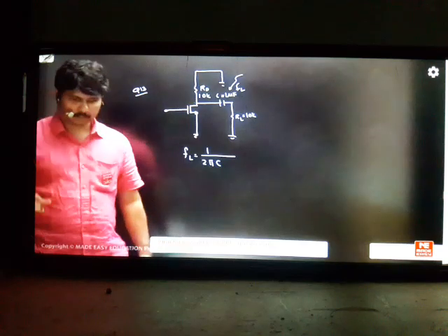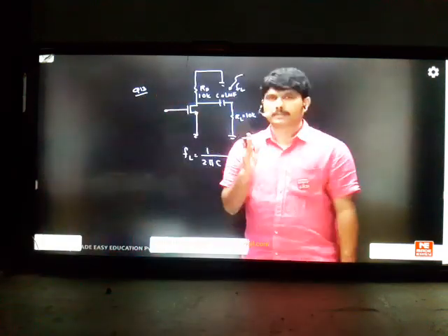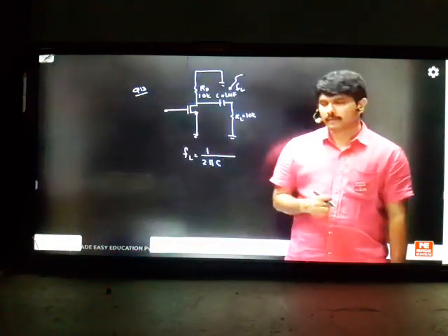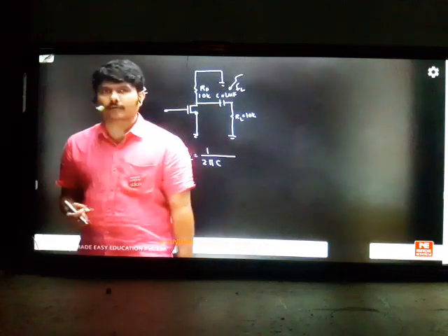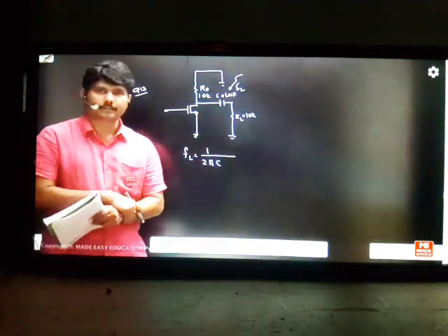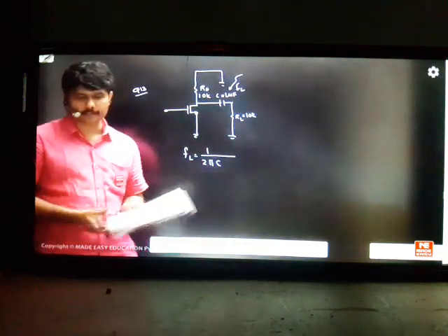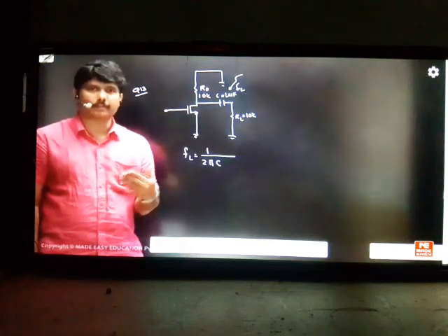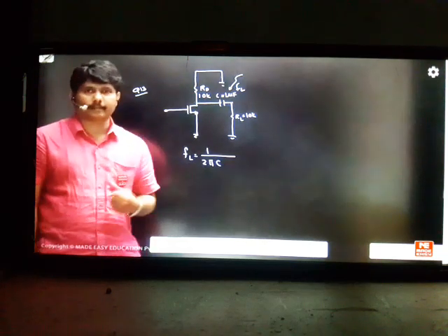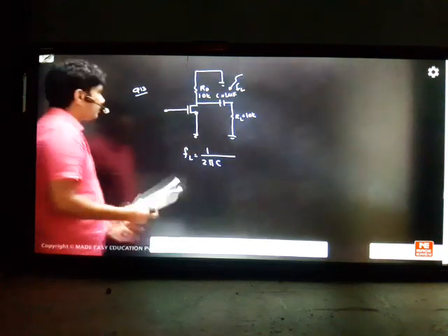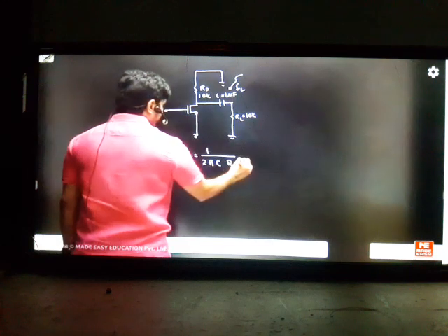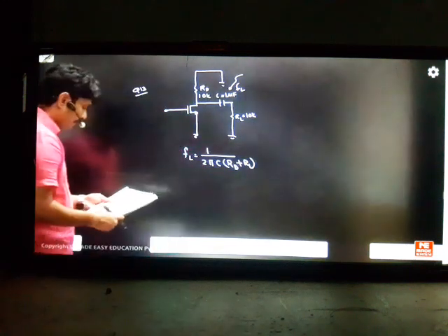So active loads के लिए current mirrors use कर सकते हैं, but in CMOS we are not using that one technique like that. Okay? Our technique is P channel transistor we are using as an active load. Generally active loads can be used with P bias, correct? P bias will come from the current mirrors. But in this question is asking what is your active load? PMOS or NMOS is asking. Bottom is my amplifier. Above is the load I kept. That's a P channel I have written. So this formula is known. RT plus RL will be the calculation. So this formula came from BJT classes.